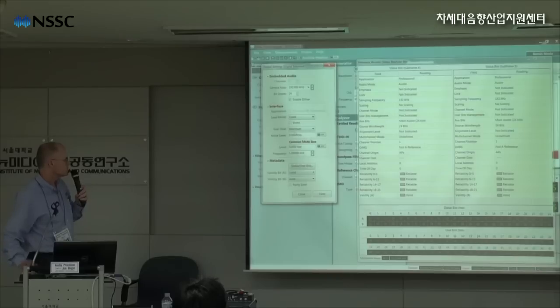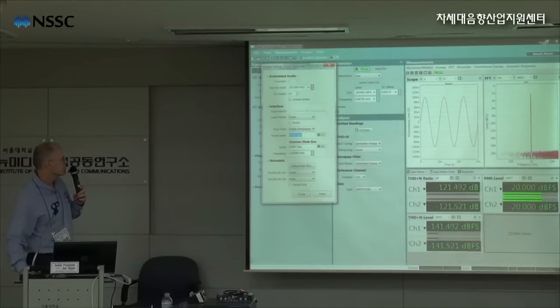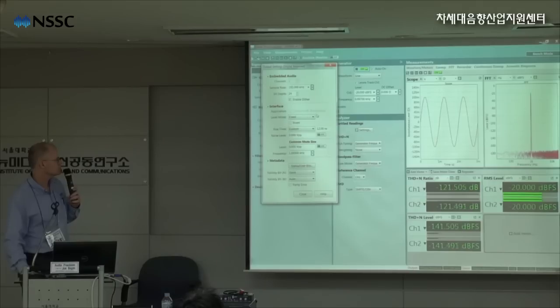This will allow you to introduce some noise on the physical interface. And you can introduce a common mode sine voltage across the two connectors of the balanced digital interface with a different voltage. You can also enter cable simulation mode where you simulate a long cable being attached to the signal. And then there is a custom rise time where you can specify the rise time of the pulses on the interface. This would be used for testing digital input devices. And you can invert the signal.